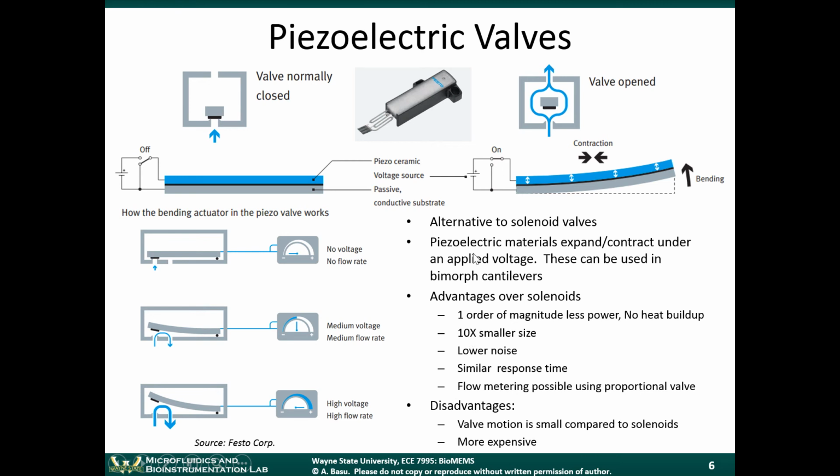So this is a faster alternative to solenoid valves. It's an order of magnitude less power. Actually, it says similar response time here, but some of these piezoelectric valves, especially the microscale ones, can actually operate much faster than the solenoid ones. So you can make that correction in your notes.